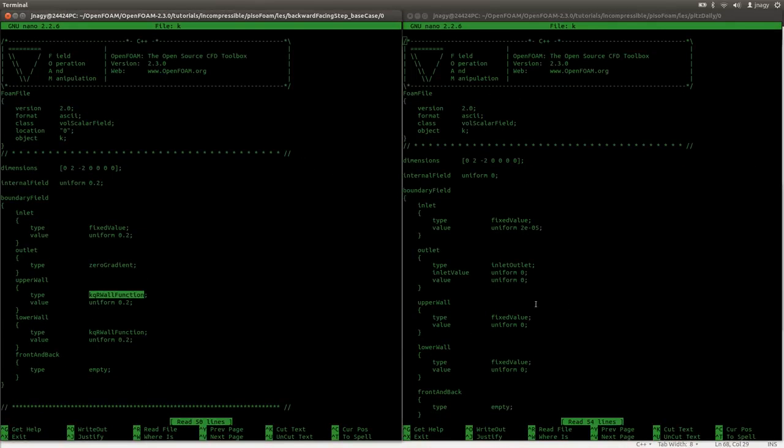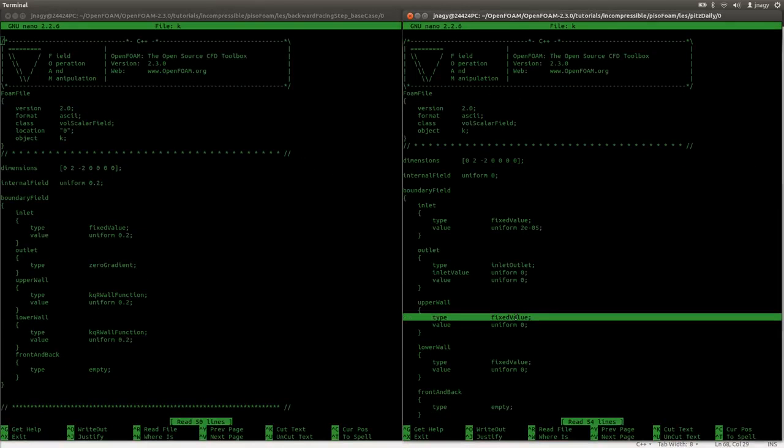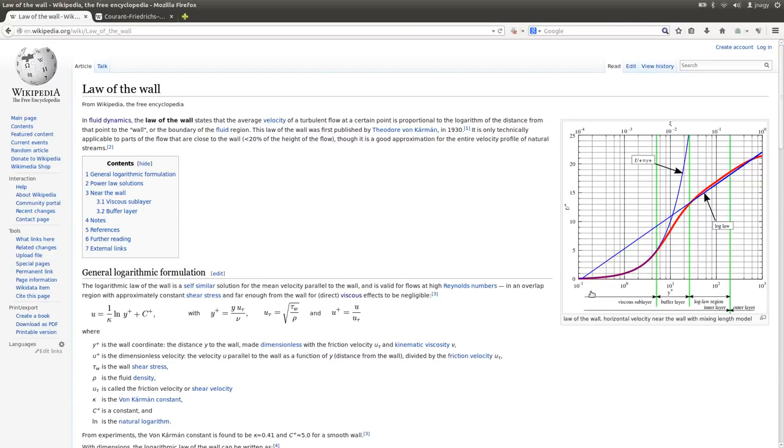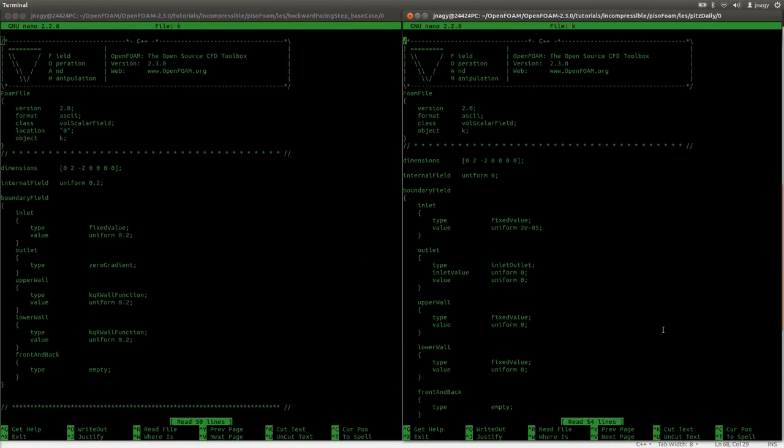And we are not using wall functions in the LES simulations, but rather we are fixing the value of k to 0. So here what we are actually assuming is that we are resolving the viscous sublayer, and since we are using no-slip boundary conditions for the velocity, also the oscillations are 0, and with that the turbulent kinetic energy is 0.